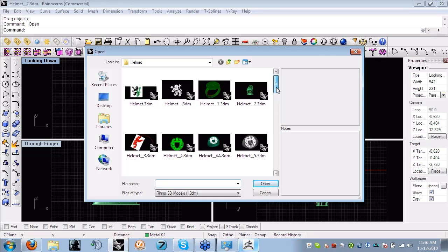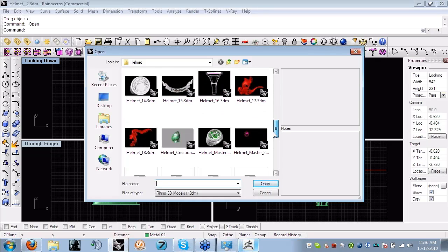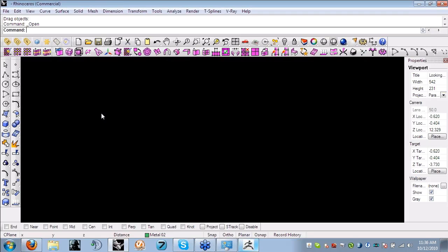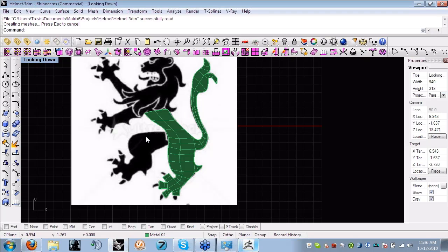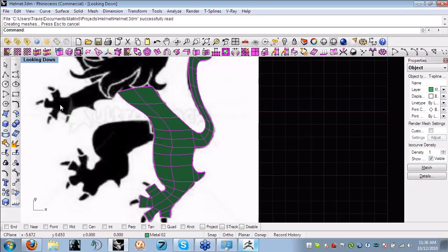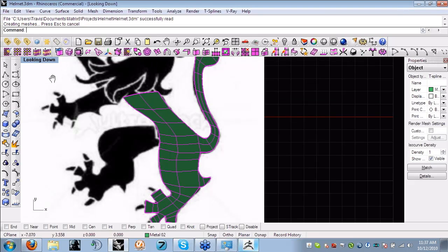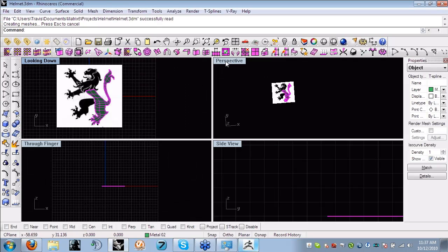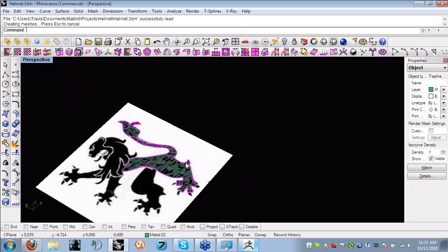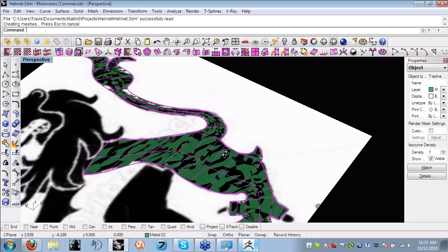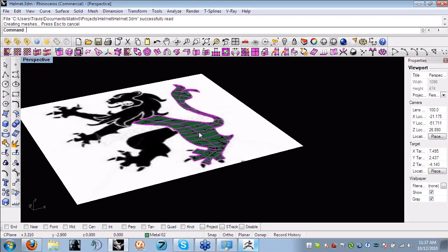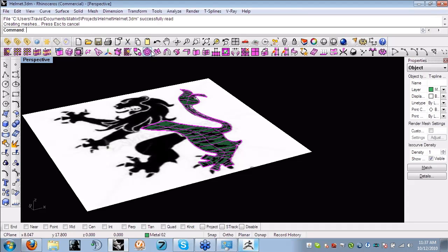Travis, one other question. You talked a lot about thickening T-splines. Could you show a simple example of how thickening works? Maybe rotating something and thickening it. Sure. When I draw all these out, this is all completely flat, and you can see it's just laying on top of this flat picture frame here. And then once I grab the thicken command, you can just pull it up.